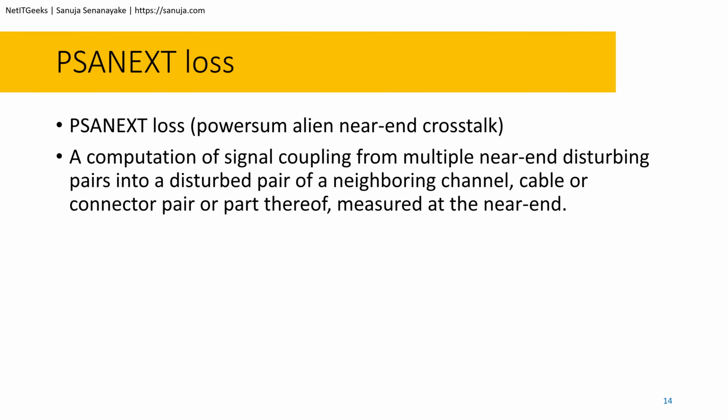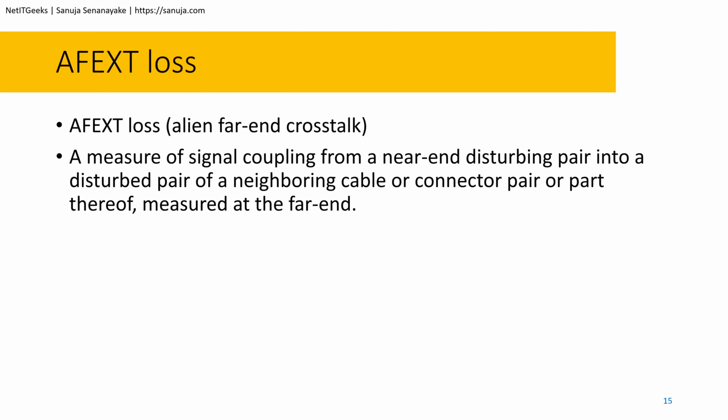PSA NEXT loss, which is basically the Powersum alien near end crosstalk. Again, the definition is a computation of signal coupling from multiple near end disturbing pairs into a disturbed pair of a neighboring channel, cable or connector pair or part thereof, measured at the near end. Again, all of these have similar characteristics to what we have discussed in the previous slides, so I'm not going into any more details other than the definition itself. Basically, these are all losses, right?